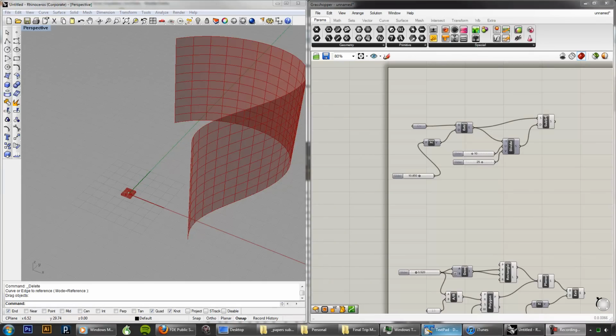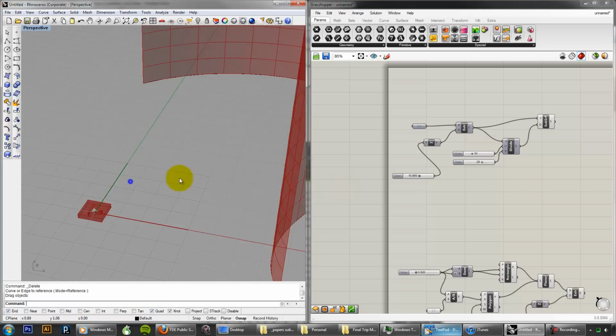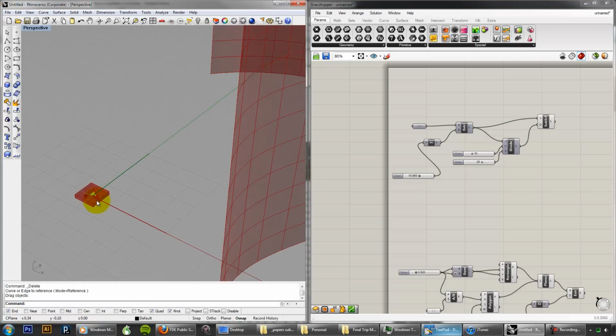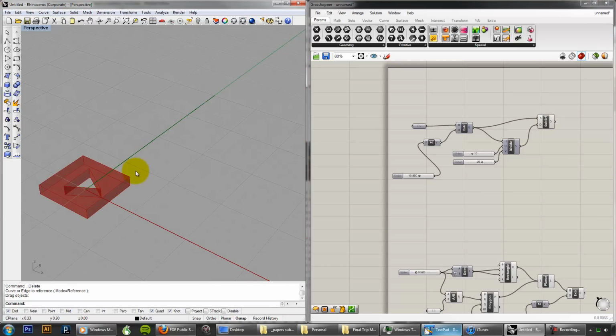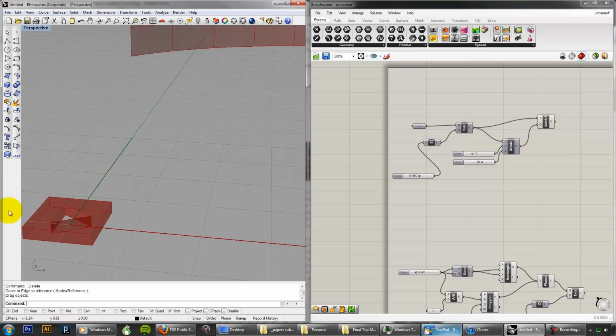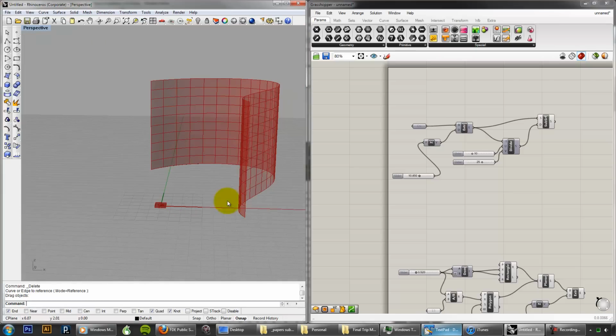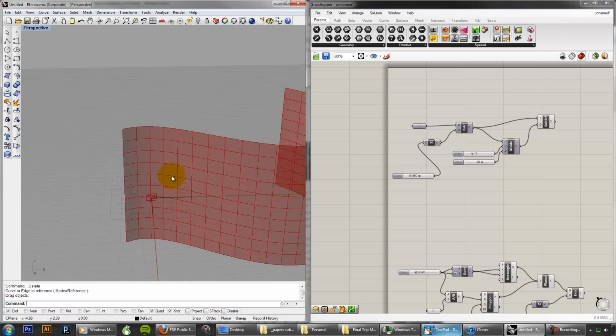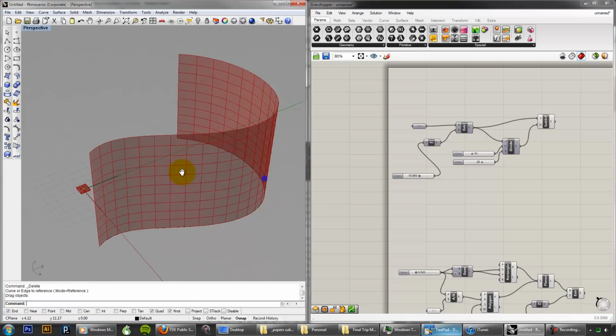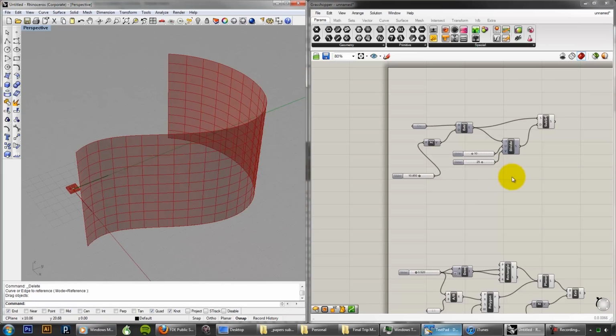So for this last pattern, I'm going to talk about something called a morph box. What this allows us to do is take some arbitrary geometry and morph it according to a tile pattern. There are different uses for this, but mostly what we see is an object that fits within a square box. It doesn't have to be exactly a rectangle or a square. It could be a donut or a sphere or something, but it fits into a bounding box that's basically rectangular. Okay, and what I've got here in this sketch are two patterns that we've seen before.